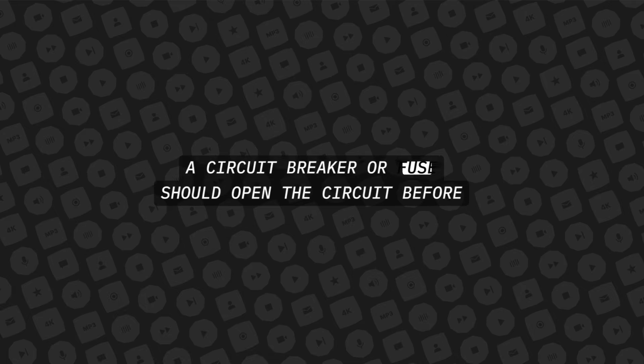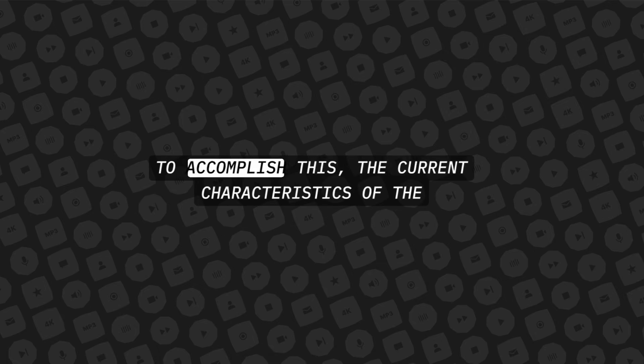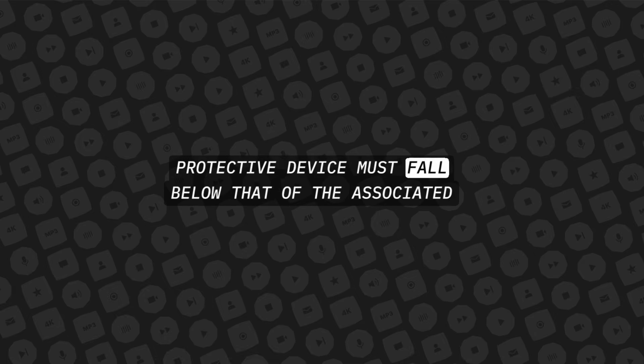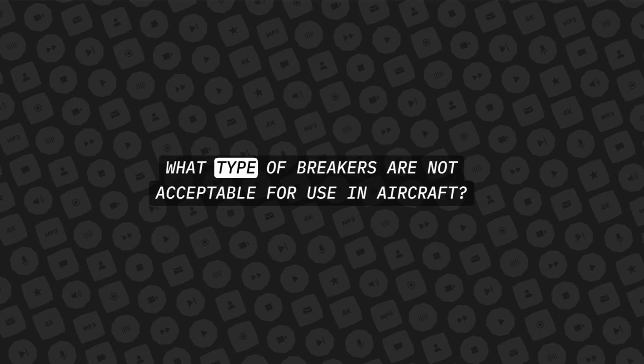A circuit breaker or fuse should open the circuit before the conductor emits smoke. To accomplish this, the current characteristics of the protective device must fall below that of the associated conductor. What type of breakers are not acceptable for use in aircraft? Auto reset breakers. What is a slow blow fuse?